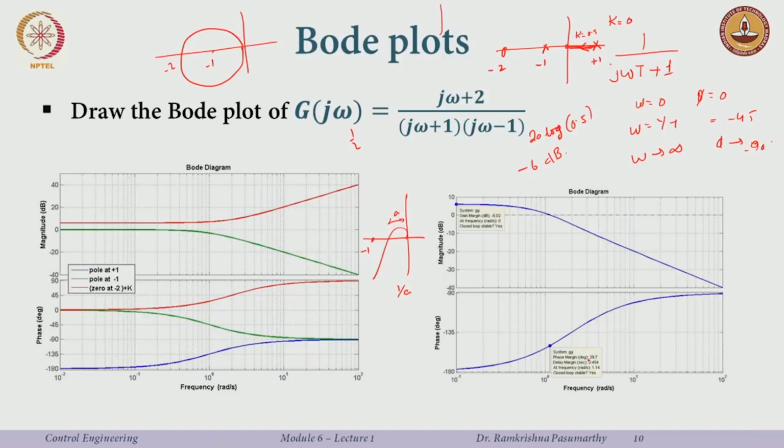I think MATLAB will tell you this directly. Of course, lots of things will come up again while we are dealing with stability and also minimum and non-minimum phase systems. At the moment, you can understand this from what we learned through the Nyquist, that I really have to decrease my gain k, because the open loop gain is 1. And from the root locus it is obvious that I start from an unstable system and have to make it a stable system, and the closed loop is stable here, unlike the previous case. That is what even the Nyquist tells us.